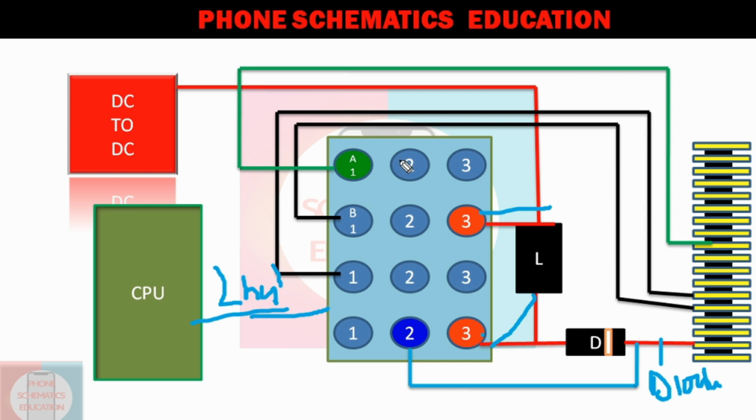So how to confirm where the fault is? This IC is faulty, this coil is faulty, or this diode. Also, sometimes the controlling section which is connected from the CPU does not work, or any line is not connected to the IC or does not communicate properly. So this line has a problem. Now I will tell you about this controlling section.